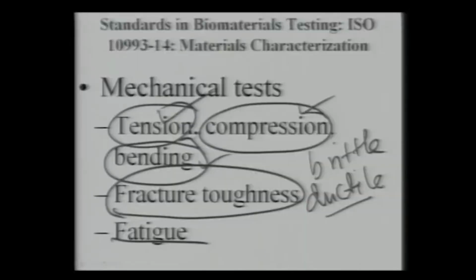Now fatigue testing is also important, for metallic materials, for example, you have the S-N curves. Fatigue testing means that when a material is under repeated stress cycles, what is the maximum stress level that the material can withstand before fracture. When you do a simple tension test, you are pulling a material from two ends, giving uniform stress throughout the testing. But fatigue testing means you are not giving uniform stress; your stress cycles are sinusoidal or cosine or some typical repeated or reverse stress cycle, and then you assess the properties of this material under the repeated stress cycle.